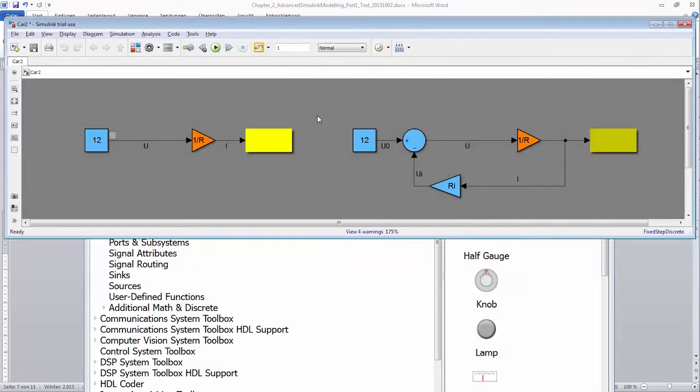And right, we see with the ideal source, the light is brighter. You see a loop at the real voltage source. The challenge here is that there is no block without direct feedback to start your simulation. Such loops are called algebraic loops.